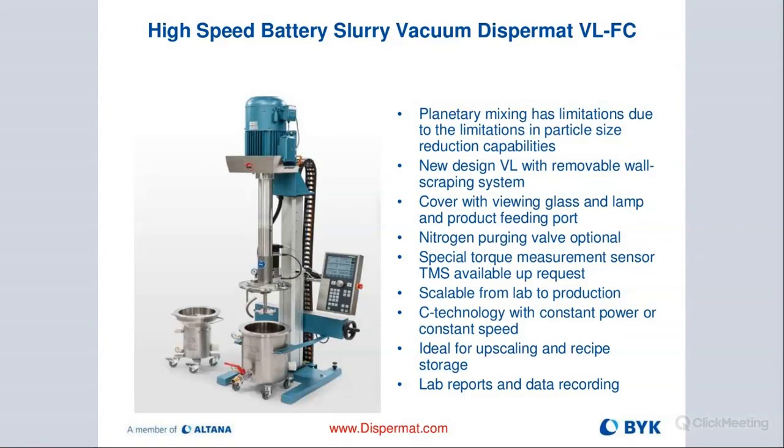And between those two ranges, the H1 and H2, we can operate the disperser or the media mill. If someone were to lift up or push the up button, then the disperser will automatically stop at that point, so that there are no moving parts or blade outside of our container to throw product around the lab or injure somebody at these high speeds. So these are two very key safety features that are a part of all of our units, and ensure that everybody is safe when they operate within these parameters.